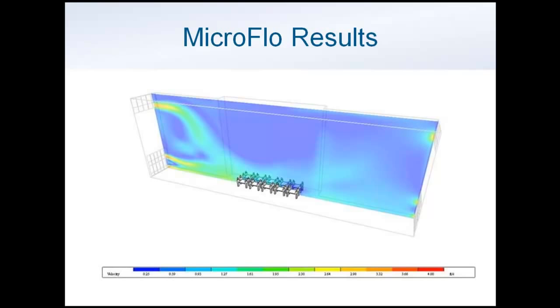And the important thing here is that the air coming through the east and west openings is indeed getting to where the people are there on the first floor so the people can breathe. And this was a very nice visual result for us to have as, again, proof of concept. And we used the MacroFlow results to have the boundary conditions in this MicroFlow CFD model.